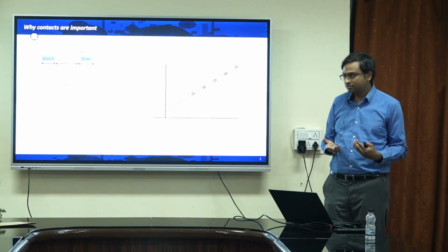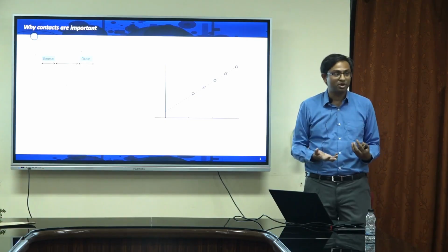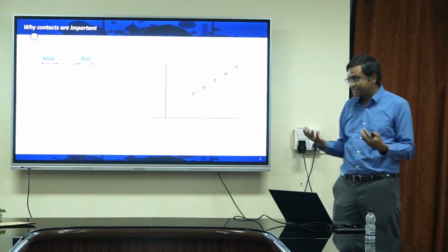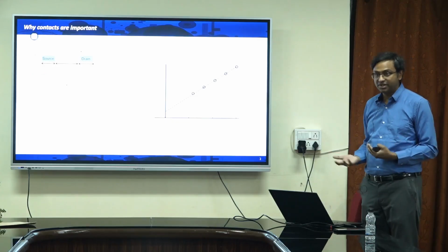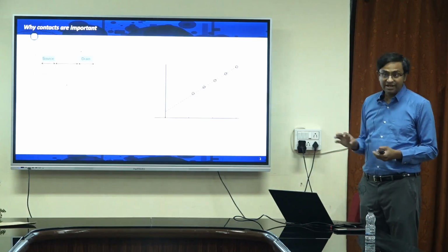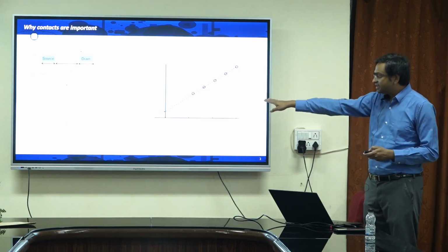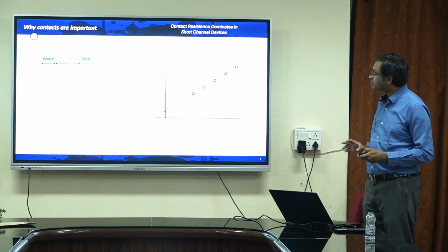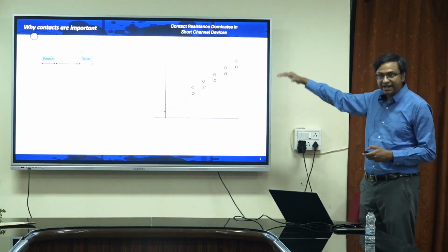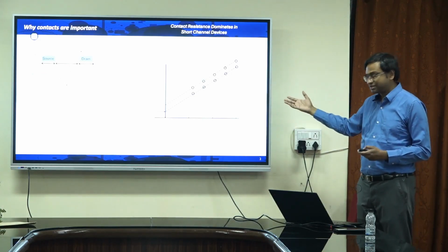Make sense, right. So therefore for short channel devices, contact resistance is even more important, for scaled transistors, and we are talking about transistors of channel length 10 nanometer, 20 nanometer. So there the contact resistance becomes very important, because the intercept is the contact resistance, that is your 2RC. If I have a higher contact resistance, then my entire curve will shift. So that will increase the total resistance of the device.